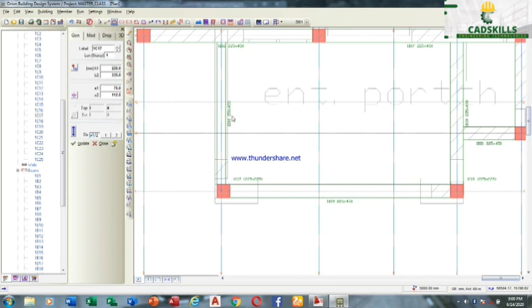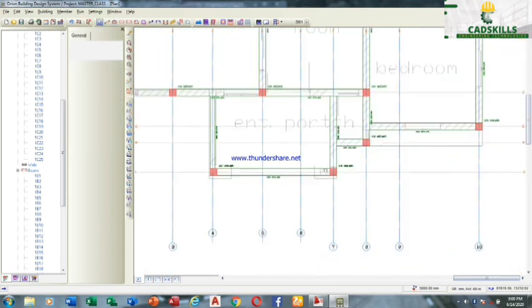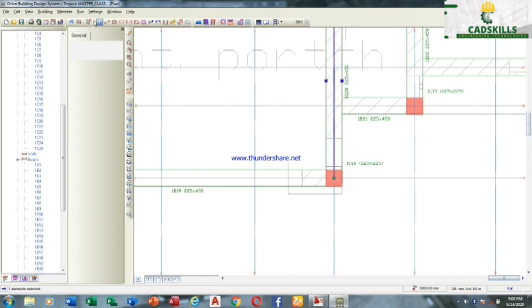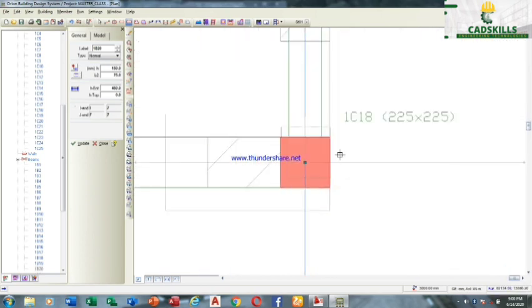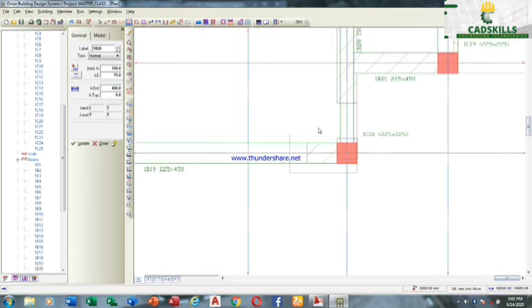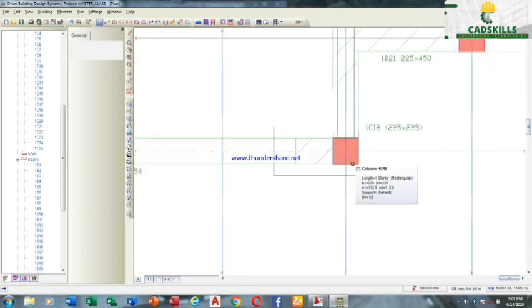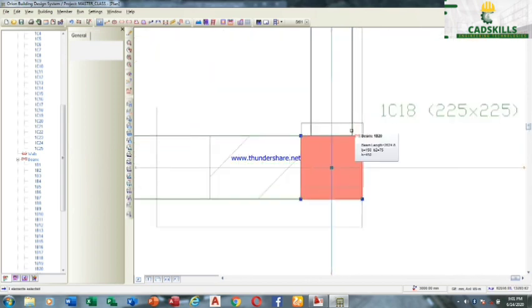Okay, let's do the same thing for this side. Make the beam a 150 beam. If you are given a wall that has a beam of 150, you must not do it like this. You set the 150 beam before you put it. I'm just doing this because I've already done this and I need to show you. Okay, now this column, look at it. Now look at this beam. You have to shift this column to align with this beam, thereby this side going inside more, defining the centricity here.